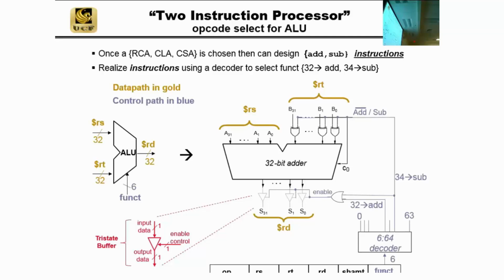It's indeterminate. There's a transistor in here trying to drive this to 1, and you're going to burn it. You'll end up burning out the transistor eventually. This transistor is trying to make this line 1, but actually it's shorted to ground. So that transistor is shorted out, and it just keeps dumping current to try to make this a logic 1. You can't. So the point is this: we can never connect two Boolean outputs together.